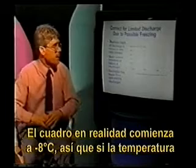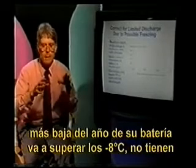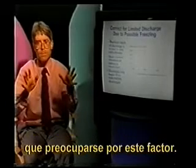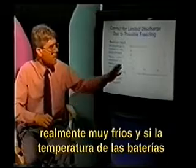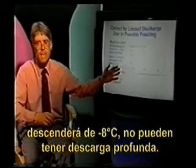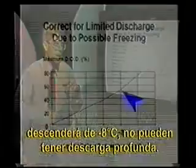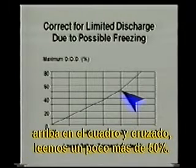The chart really begins at about -8 degrees centigrade. So if your battery coldest temperature in the year is going to be warmer than -8 degrees, you don't have to worry about this factor. But for those that are installing batteries in truly cold climates, if the battery temperature is going to get lower than about -8 degrees, you've got to back away from a deep discharge. Notice that, let's say at roughly -20 degrees C, the battery gets that cold, leading up off the chart and then across, we read a little bit more than 50%.